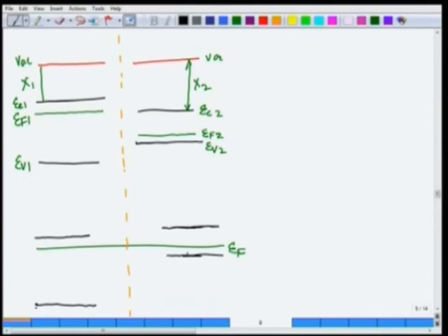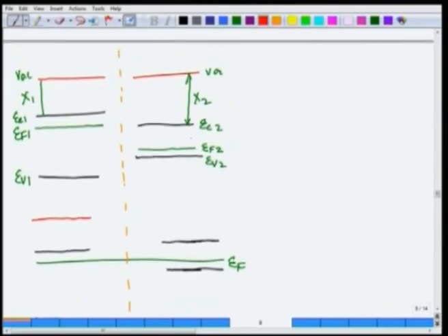Now, if you want to draw the vacuum level, then we have to draw the vacuum level. That is the most important part to draw. So, I am going to draw, at a distance of about this much, psi 1, this vacuum level. So, here is the vacuum level I have drawn, and from here psi 2, remember psi 2 is bigger than psi 1. What we have done is, we have imagined that we have lifted this part of the curve higher, up to this Fermi energy has been lifted up to here.